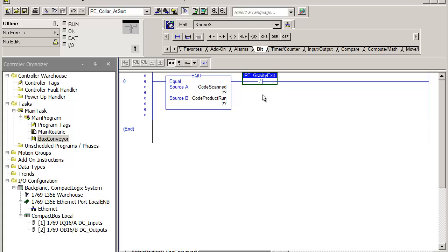So I don't know if you're familiar with photo eyes or not, but most of them you can select light operate or dark operate. And they give you the inverse operation as far as it being a switch. And it's the difference between it turns on if something blocks the photo eye, or it turns on if nothing's blocking the photo eye. So in this case, we're going to use a true if off because we're looking at the conditions in order to release the stop. So if this photo eye is clear, meaning it's off, therefore this would be true.